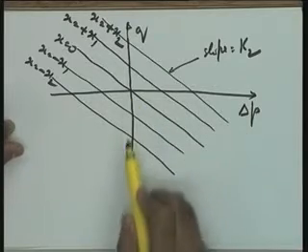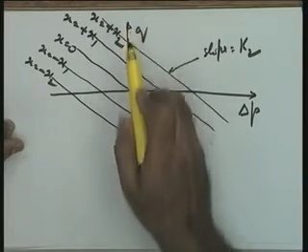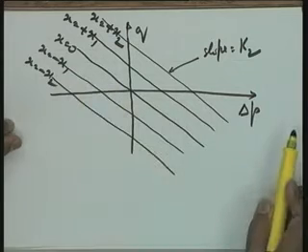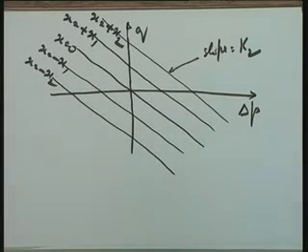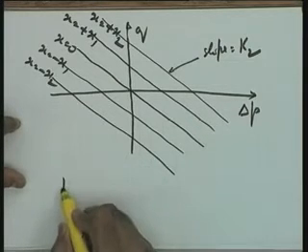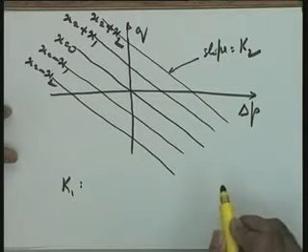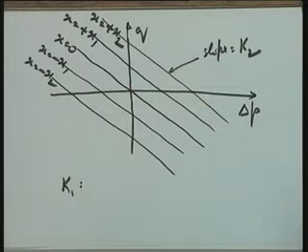Fine. Similarly, for the other slope, if you take a constant pressure, let us say del P is equal to 0, you plot a curve Q versus x and get the slope of Q versus x, that is the value K1. So K1 and K2 are the two parameters. K1 let me call the valve gain, and K2 the pressure coefficient if you like.